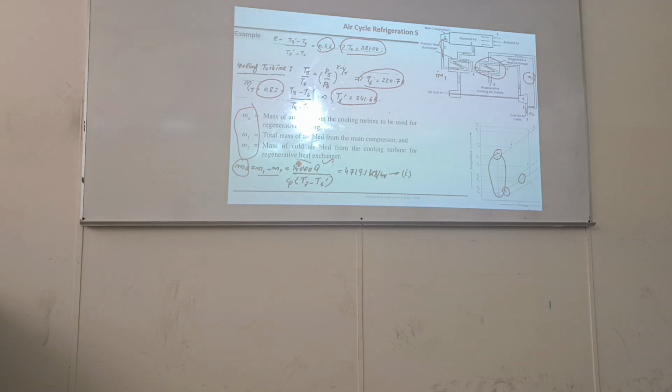Here, look, he is multiplying with 14,000 to convert this tons into kilojoules per hour. So I would recommend you to keep your life simple. Always use tons multiplied by 3.5 kilowatts. Keep it in kilowatts. If you follow the exact solution in the book, sometimes he is using kilojoules per hour, in some questions kilojoules per minute.